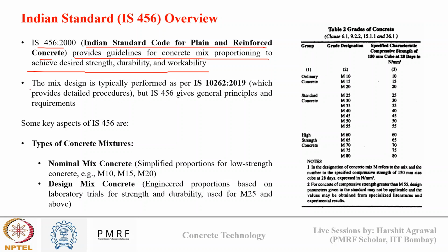And mixture design is typically performed as per IS 10262, which provides a detailed procedure. IS 456 will just give me basic general principles and requirements. The actual mixture design procedure is there in IS 10262.